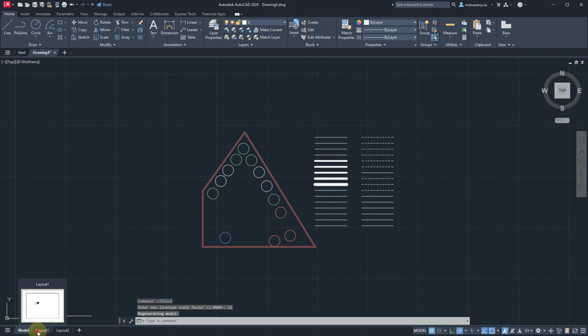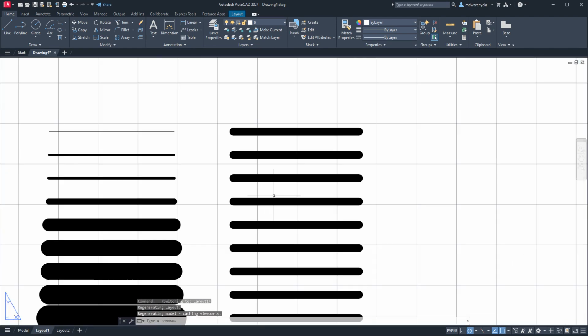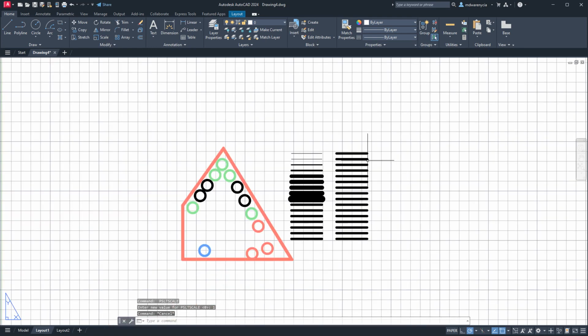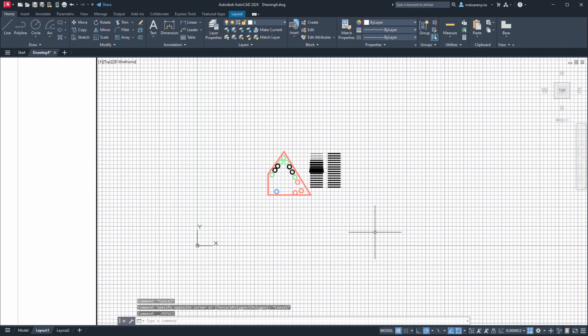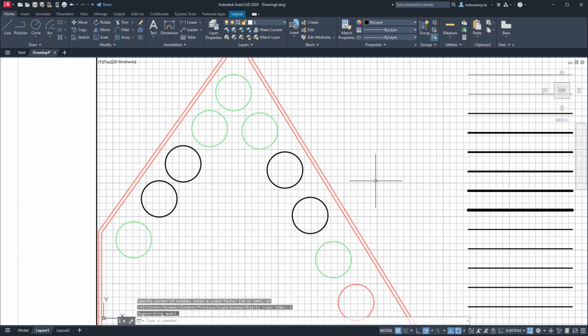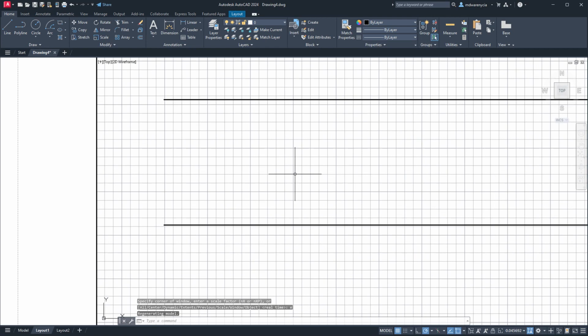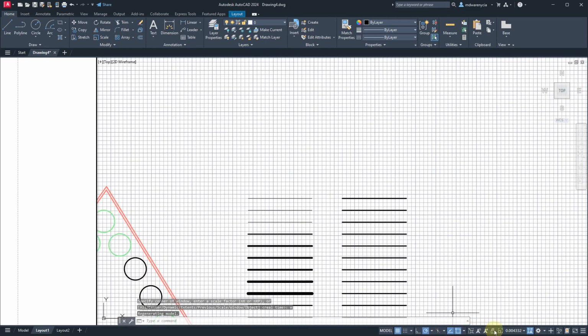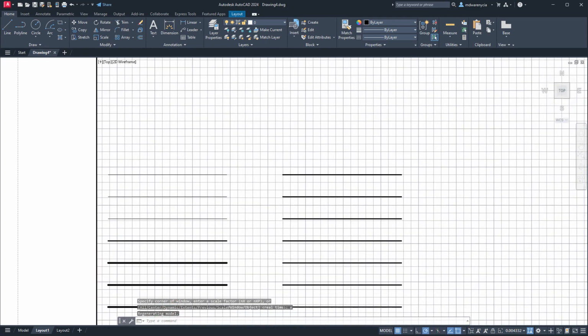Now it shows it there, and then the next problem is we usually don't see it here as well. So then we'll do PSLT scale, which is Paperspace line type scale. And this one is on or off. So we'll want that on, and then, oh, it's just because of the size, I think. What is this? Ugh, quarter inch. Let's see, enter. Go back to quarter.